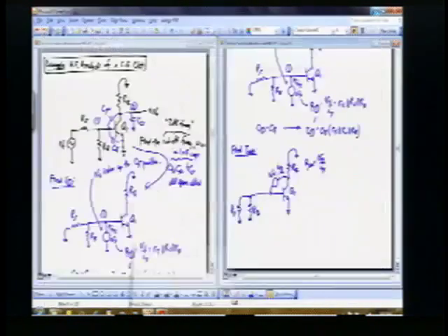Okay, so it's equal to RB circle here, which is the resistance you see at the input, shunt with the input. Okay, plus RC circle, which is all the resistance in shunt with this node at the collector, plus the GM of this, and notice it should be the capital GM, okay, which in our case is equal to little gm because we have no emitter resistor, times the resistance in shunt with the collector times the resistance in shunt with the base. Okay, so that's the expression that we need to use to calculate this R mu.